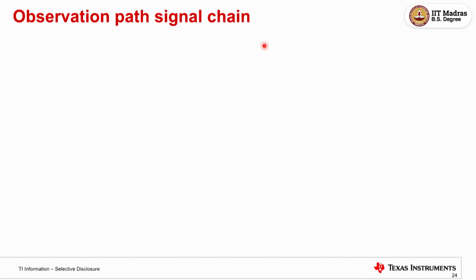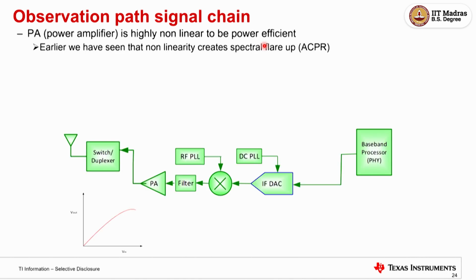We'll go back. Okay, before that, maybe a quick thing. We said what a non-linearity is, we talked about it, right? The PA, the power amplifier, is the one which blasts the signal. I said, a linear curve. The curve is linear, but it just bends because it's getting saturated. This is what you can represent as square, cube. If you put it in an Excel sheet and do a trend line fit, it will show some component of square, cube. So fundamentally it means input to output is not linear, it's just bending.